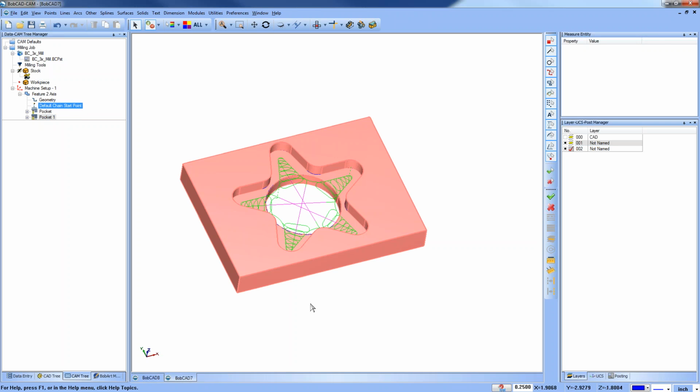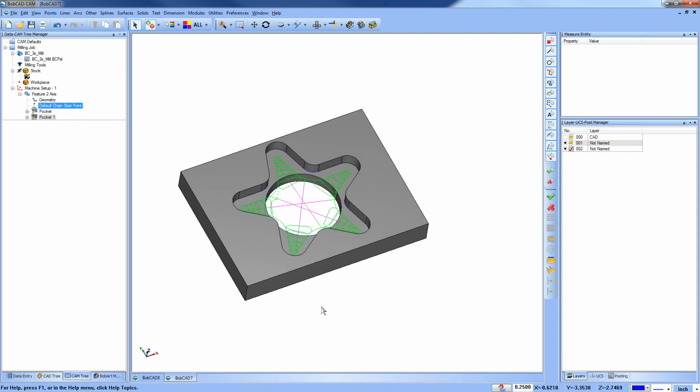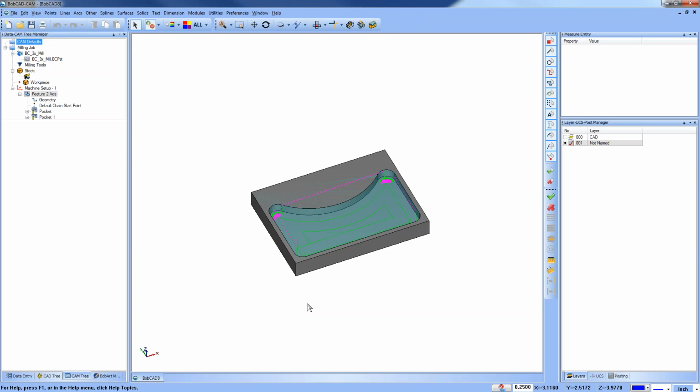You can do an inside pocket out. So this way you can work from the inside out. If you have a void, you can do that as well. And then let's see what we got here. This one, again, just coming in and picking up some corners. So you can use a smaller tool to come in and clean up what is left over in the corners.